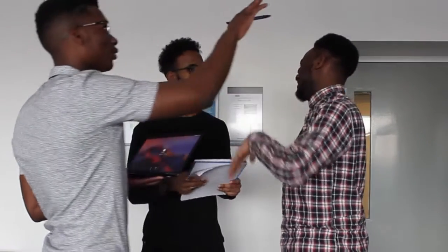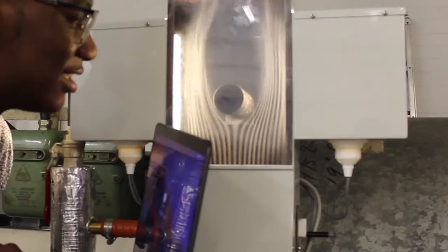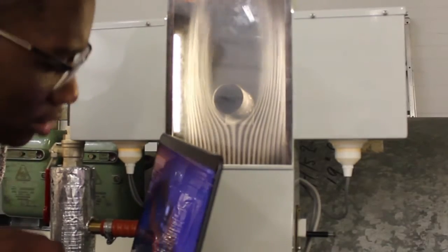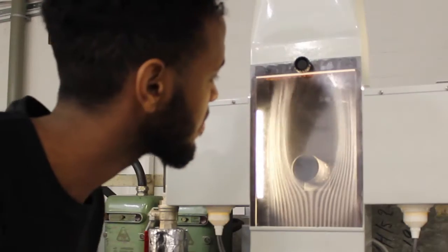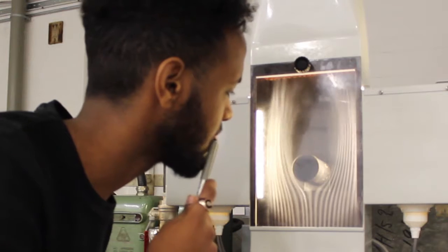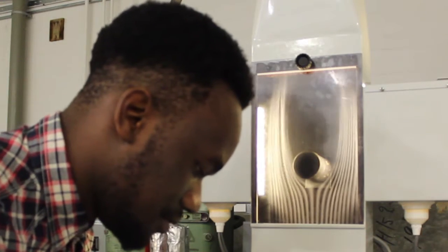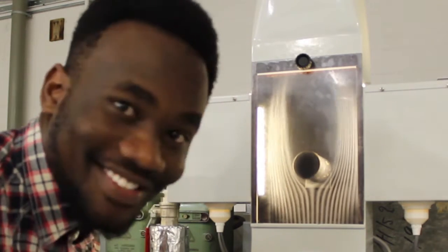With the building expected to withstand winds up to 130 kilometers per hour, Terry and his team's first challenge is to ensure that the structure can withstand these forces. After considering the wind pressure over the surface of the building, the team evaluate the wind load to be a total of 18.12 meganewtons over a uniformly varying distribution.